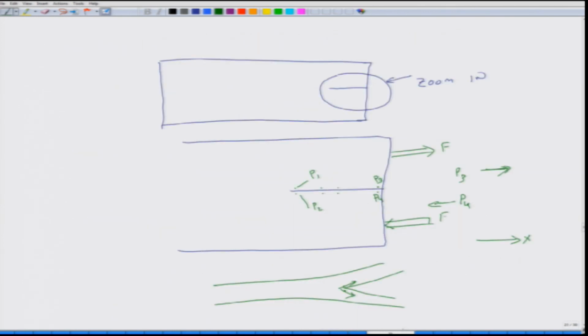If it is not continuous, then we do not do that; we do something different. For instance, here if there is no friction on the interface boundary, then we say that there is no shear force at the location P3. That may be the other condition, the extra condition we impose in case of fracture for this particular kind of problem.